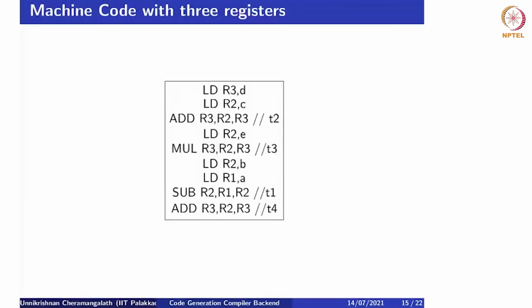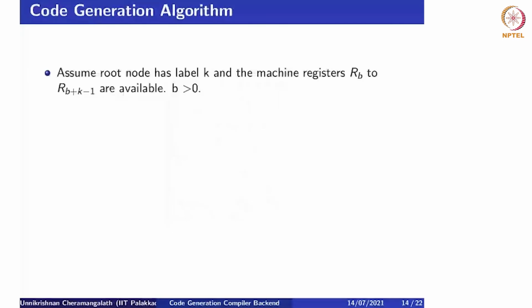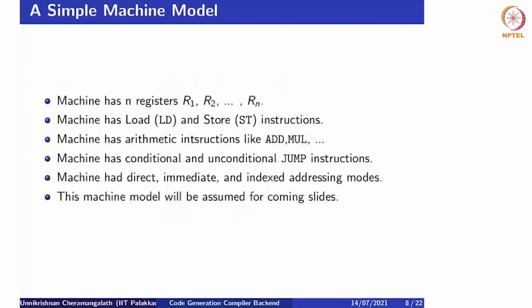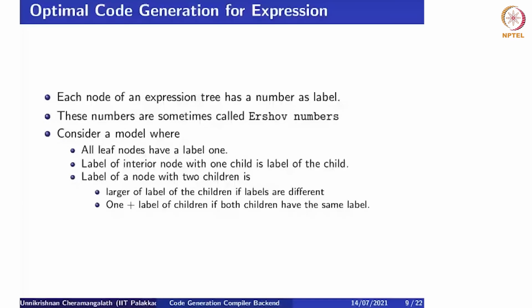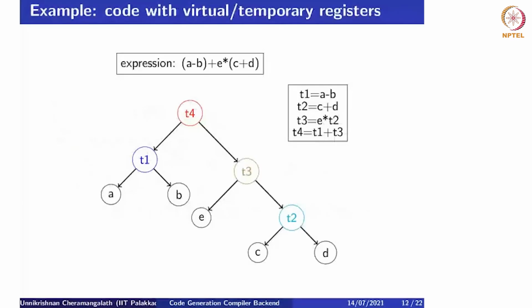So superscalar, you're talking about software pipelining? No, software pipelining is different. Superscalar means that you have two dedicated execution units. Okay, as I already mentioned, the machine model assumes only one arithmetic logic unit, to make the example simple within a one hour lecture.